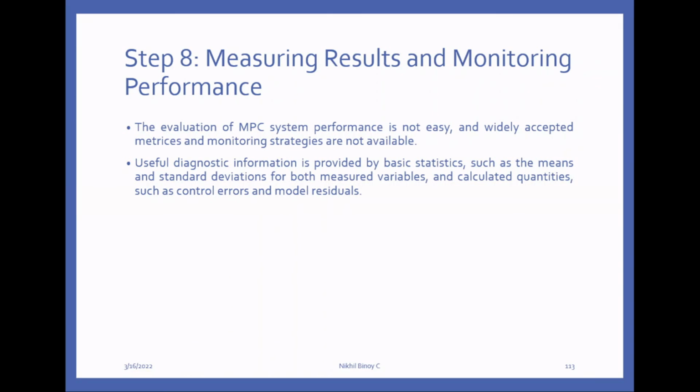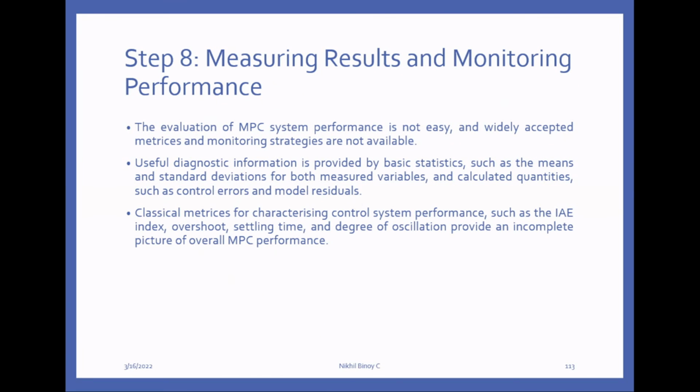After commissioning, still we are evaluating model prediction. We are measuring residuals. If you have residuals, we can take them as statistical data. We can take the mean and the standard deviation. So after commissioning, we are checking the performance of the model predictive controller.